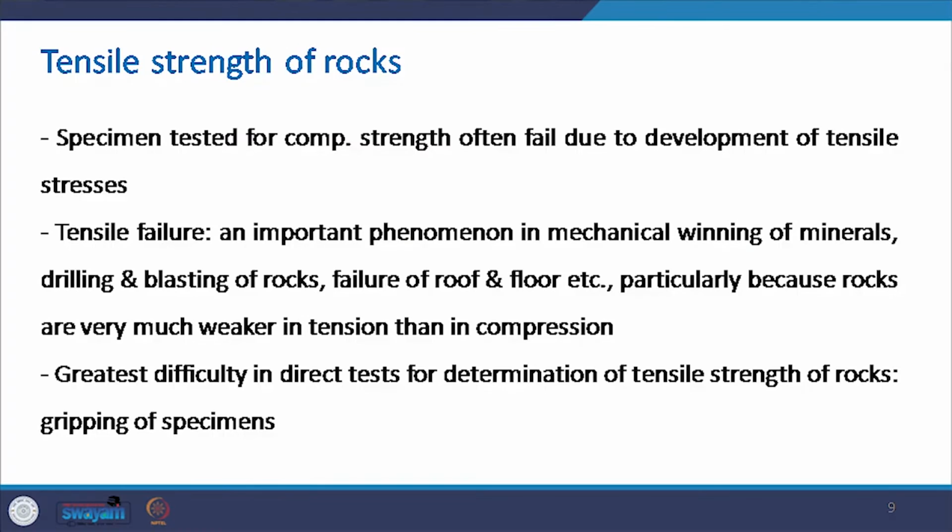I have already explained to you that, as against soil, rock possesses some tensile strength, and this is especially important in the case of tunnels or some kind of mining activities, drilling and blasting of the rocks. In the case of tunnels, it is the failure of roof and floor. Tensile stresses develop.